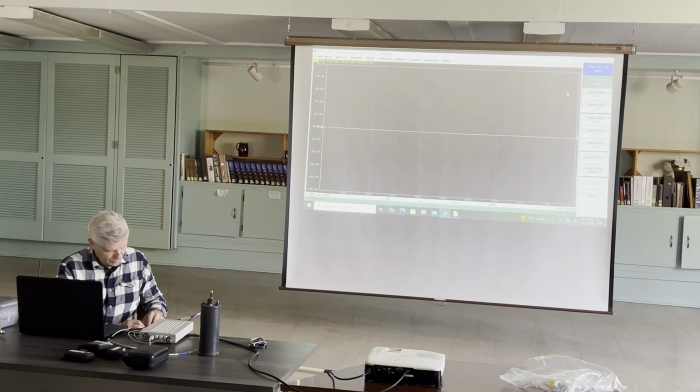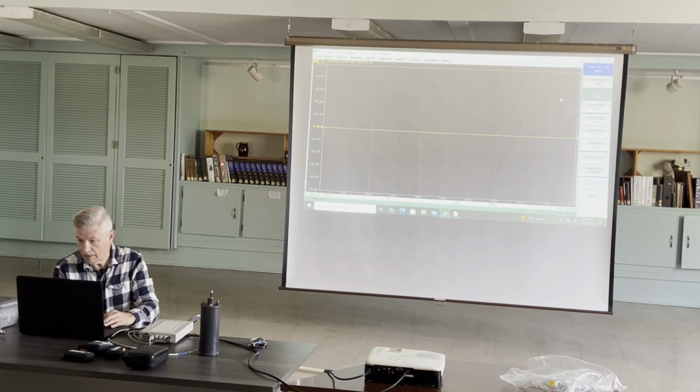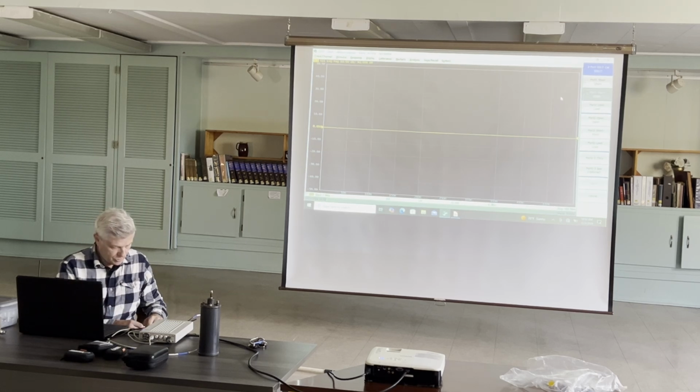And again, if you got a Rig Expert or a NanoVNA, you should be doing this every time you start the thing up and use it. Now with the NanoVNAs, they give you a cal kit, and you know what? We're going to see how good they are. At least the load anyway. We'll see how good the loads are on those.